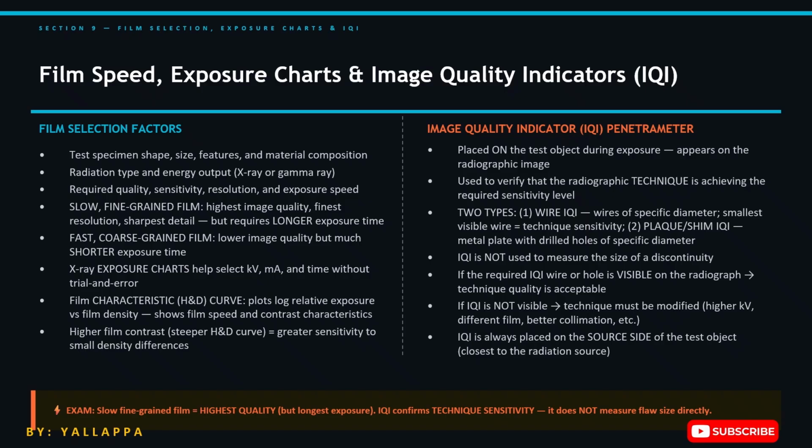If it is not visible, the radiographic technique may not be adequate. So remember, IQI demonstrates radiographic sensitivity. It does not directly measure discontinuity size.